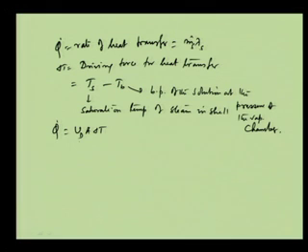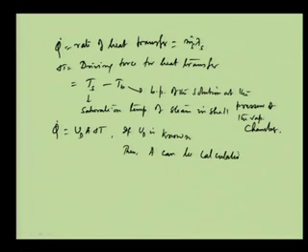So, from this relationship, if U_d is known, then A can be calculated. This is the bottom line for this case, and this driving force includes the boiling point elevation, BPE, which we have discussed in the last class.